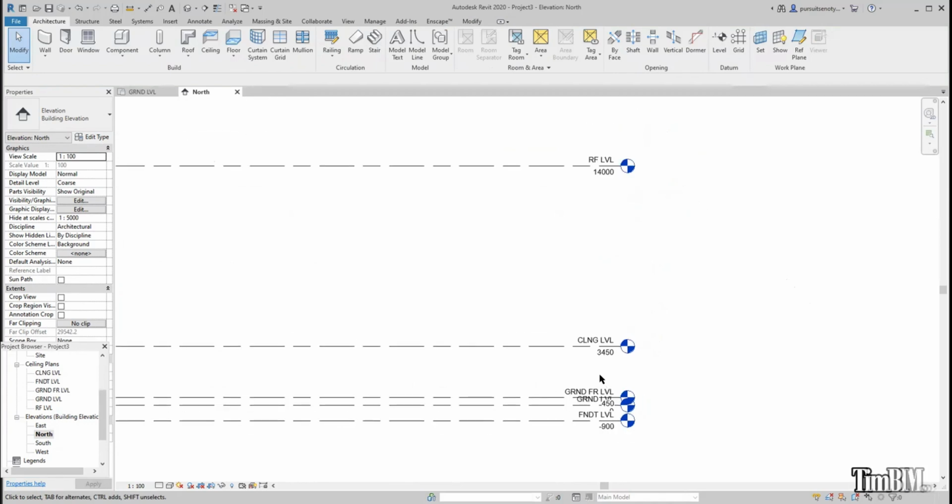Maybe I want it to be 600 above the ceiling level, so that between my roof and my ceiling there will be a little space that will allow for electrical wiring, or any conduits, or for people to be able to do any works. My cables will be passed through. So I would like to make it 600 above the ceiling level.